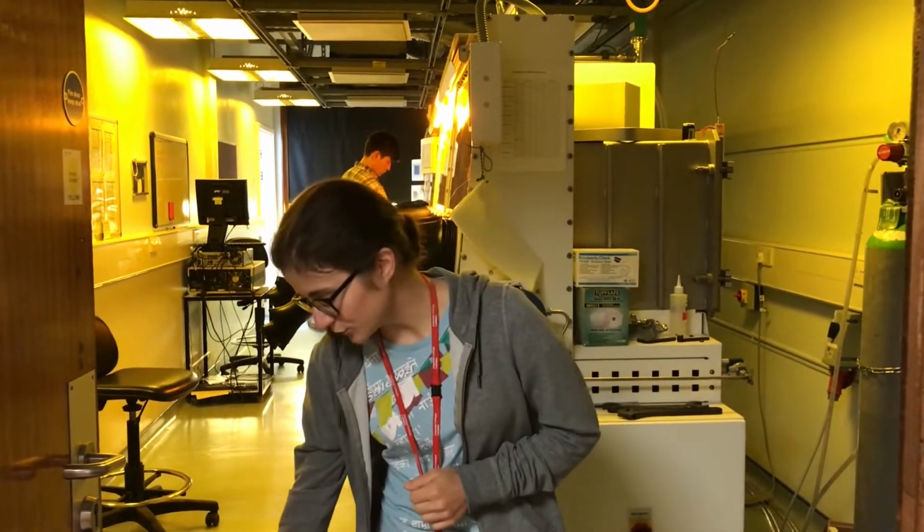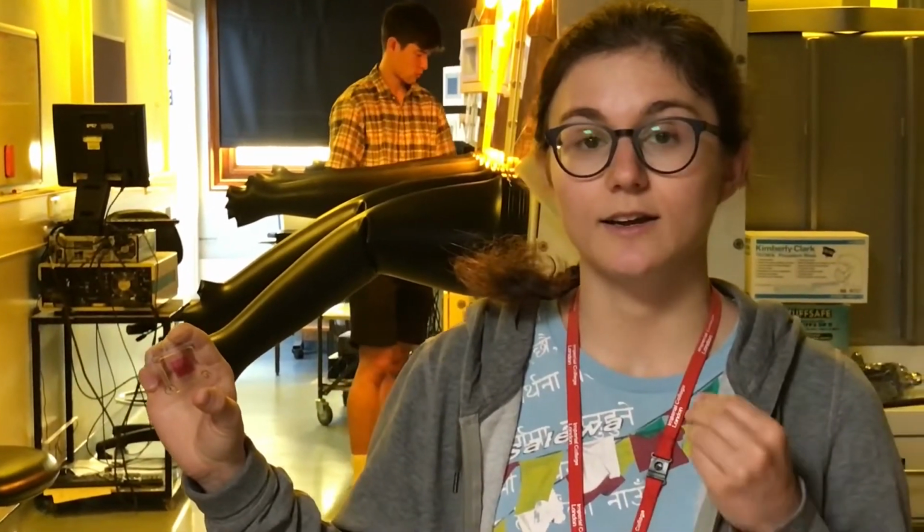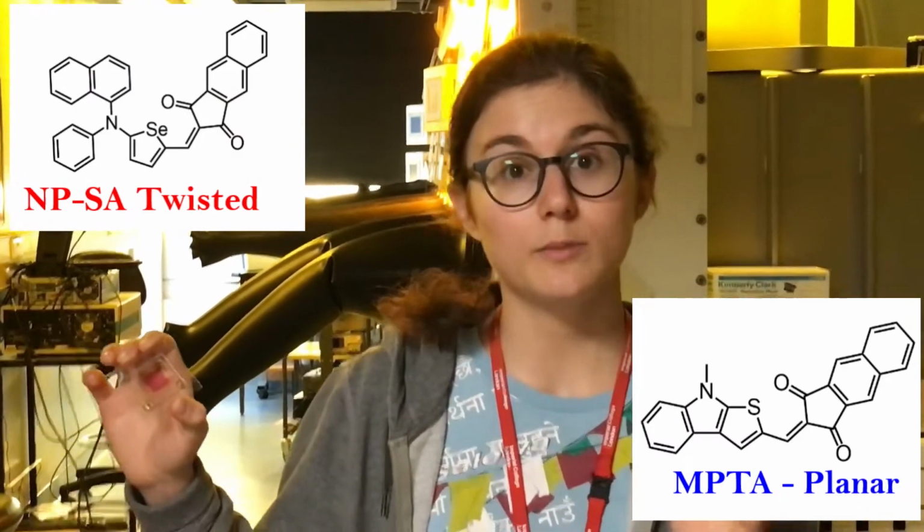And today I am going to talk about this type of devices made by Samsung. So these are basically state-of-the-art co-evaporated organic photodetectors, based on a bulk heterojunction, a vacuum deposited blend of a donor and an acceptor material. We want to extract electrons produced upon light excitation by the interfacial electronic offset between the donor and the acceptor materials in the blend. Here we are using fullerene as an acceptor and different types of small molecule as donor material.